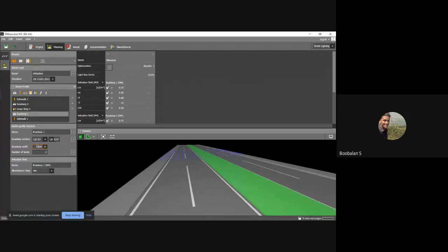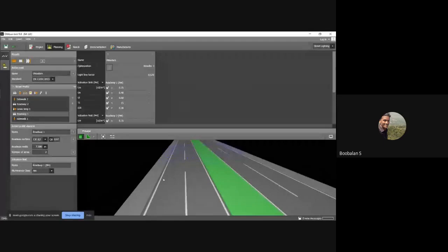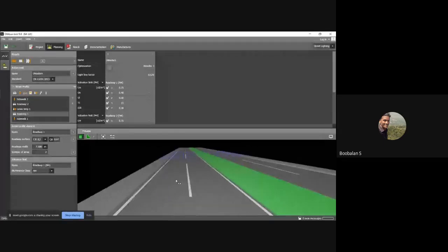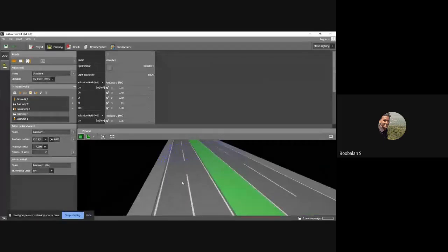The standard is 7 meters, based on that standard model. So if there are two lanes, you can go with that. At a time we'll be able to pass two vehicles. Even if I consider a bigger lorry truck, a truck is around 6 meters here, 6 meters here, 6 meters here. So we'll go with 10 meters.